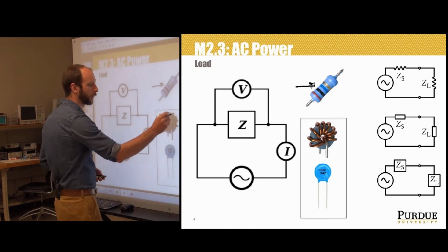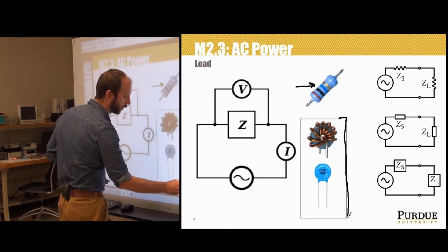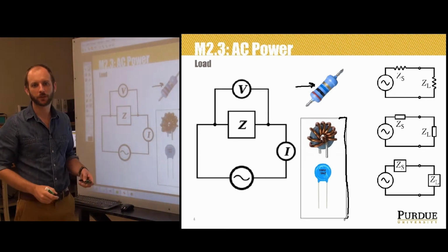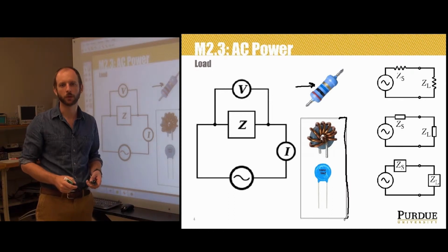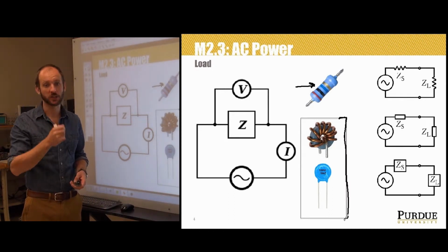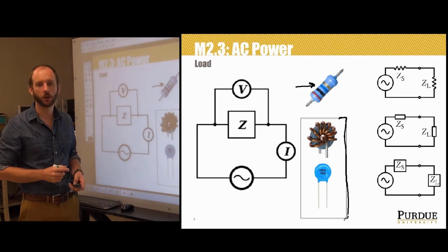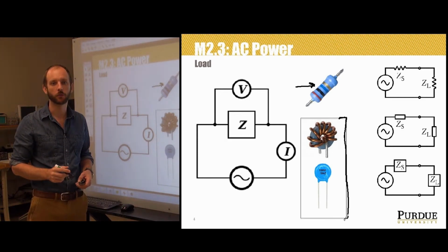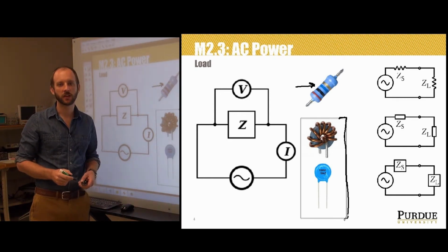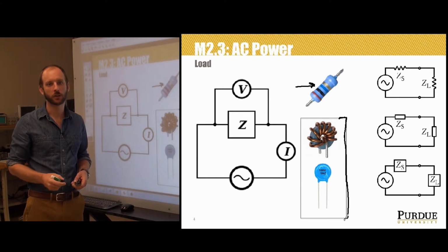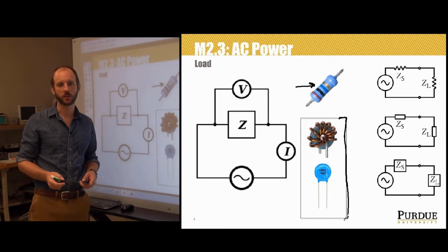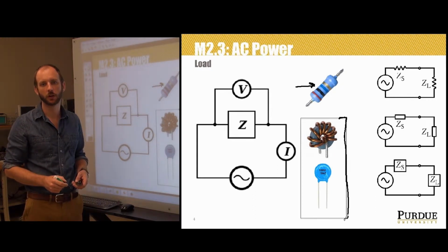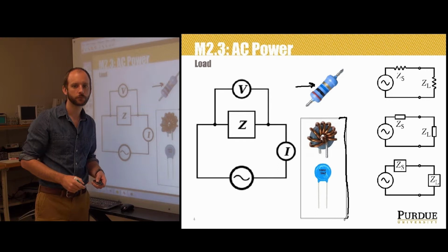Reactance, symbolized by these 2 devices here, is the property of a device to influence the relative timing of an alternating voltage and current, and by doing so presents a sort of impediment of its own to the flow of AC current, which is, we'll find out, dependent on the frequency of the AC waveform. In AC circuits, devices are therefore characterized by the combination of resistance and reactance, a quantity known as impedance, which is the opposition that a circuit presents to the passage of a current when a voltage is applied.